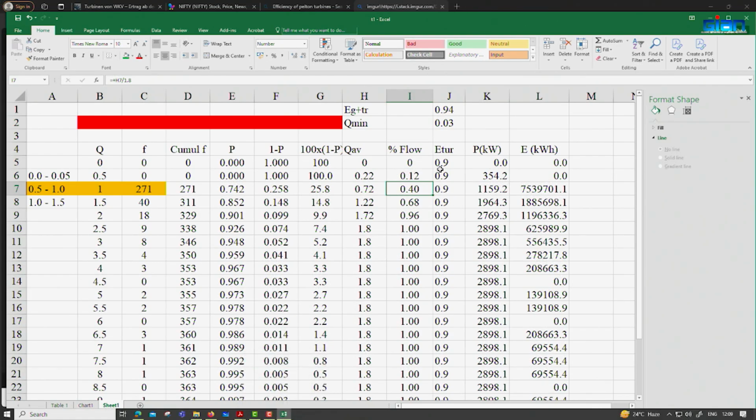Now, the Francis will have a little lower efficiency, no. Therefore, the total energy generation might also be affected. You can see there are 200 data points, 200 days, where the percentage flow is 0.4, right. And if the efficiency is 0.6 during those large number of days, your energy production will be hugely affected. Now, let us put it and see.